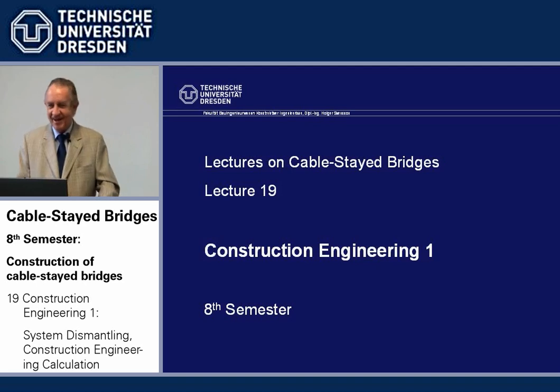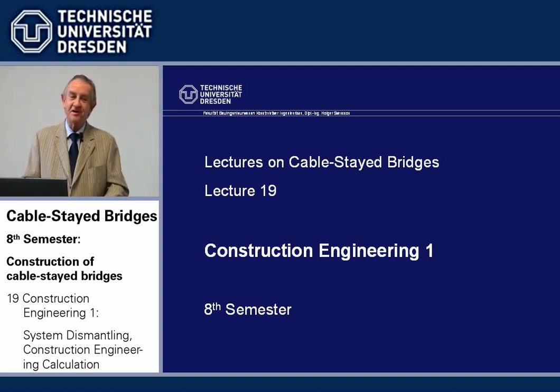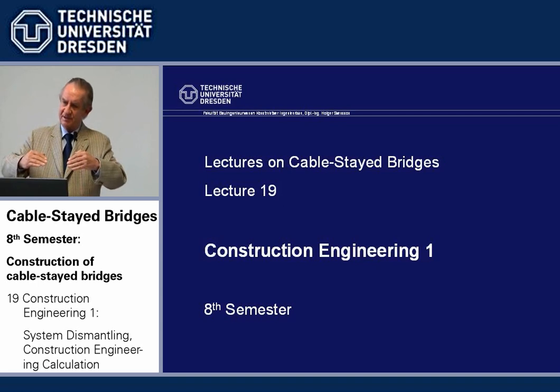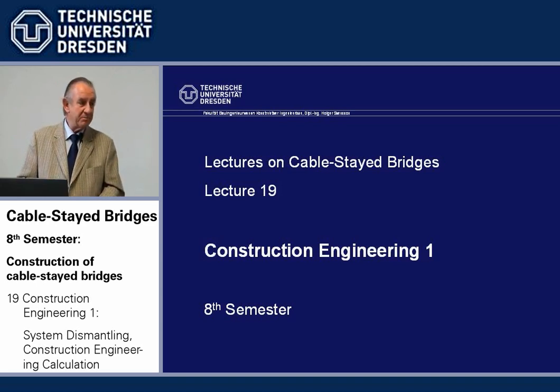And I had to do it, with very limited computer systems at that time. Strudel isn't a program which is really fit for cable-stayed bridges, but that's all we had. And the numeric preciseness wasn't all that. So we had to do the all-important final stage by hand. And then Strudel couldn't add up changed systems. The system changes from one construction stage to the other when we dismantle it, and Strudel couldn't add up different systems.